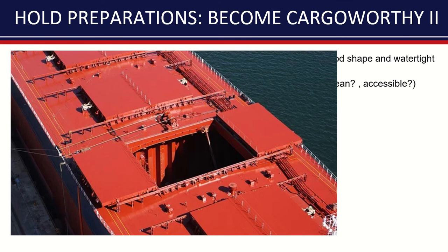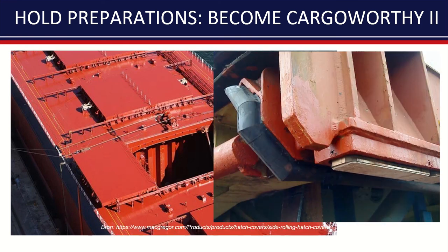Here the hatches of a big bulk carrier, and here you see the sliding pads and the rubbers. It all needs to be in good shape, and regularly it needs to be inspected, and usually it's done when the holds are open, otherwise it's difficult, of course. So it's regularly done when doing a new trip, a new voyage.